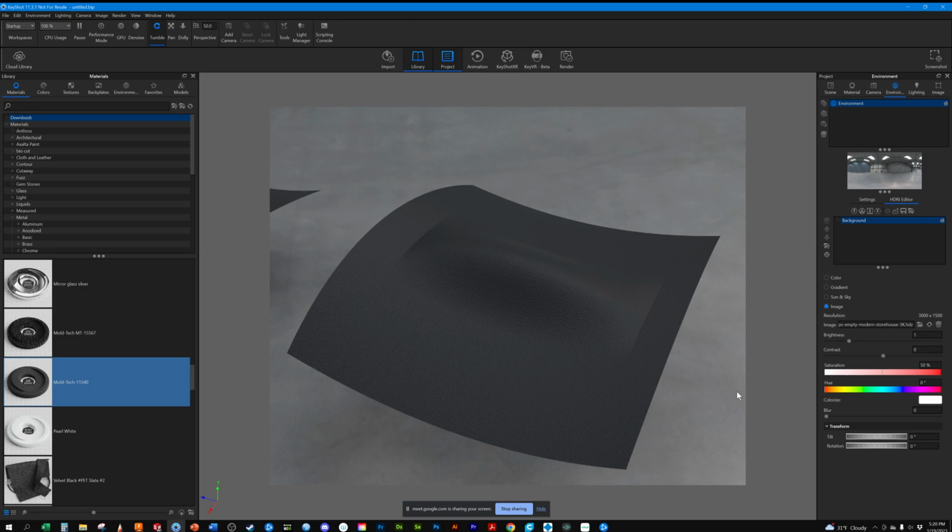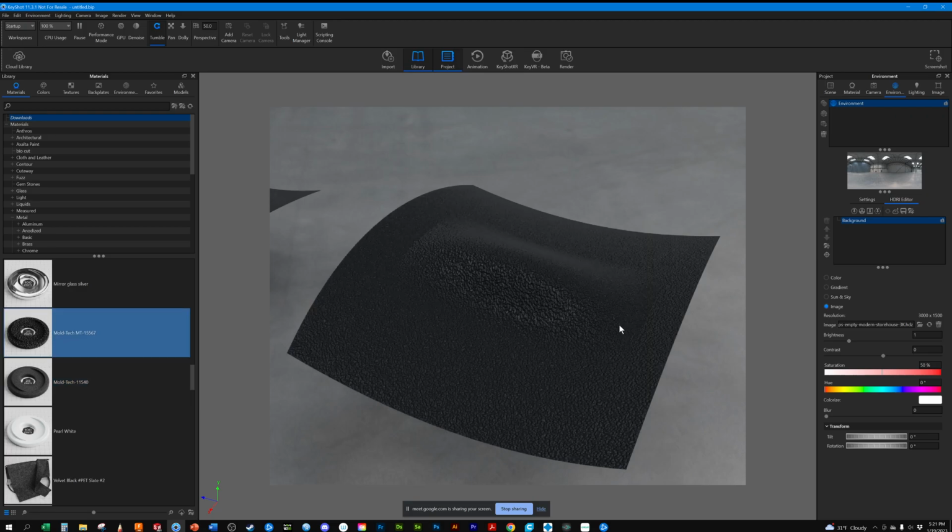Now here's something that is always dangerous when you're surface modeling. I always like to understand, especially depending on how far, what is my manufacturing? Is this going to be injection molded? Before I start designing, what are we thinking? What are our parameters? This is going to be injection molded. Oh, okay. Or this is going to be rotational molded. Oh, okay, a little bit looser controls on that. This is going to be something in the back of the truck bed. It's going to have a heavy texture.